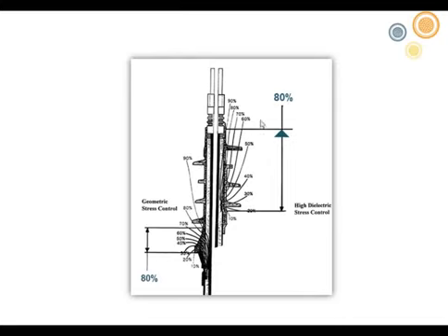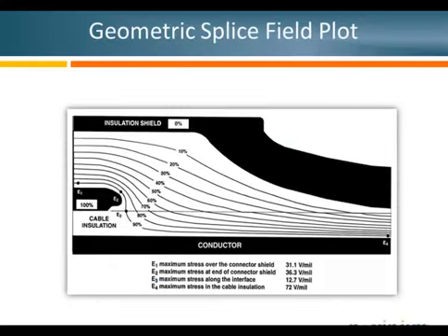Whereas because your stress is spread out more here, you have lower surface stress the whole way, therefore can meet the performance test requirements and get better field performance with a shorter termination because of that lower surface stress. Therefore, not flashing over, not breaking the air out around it as readily because it has lower stress there.